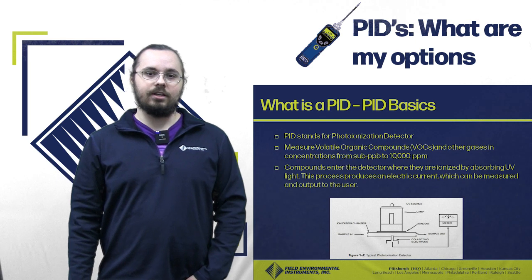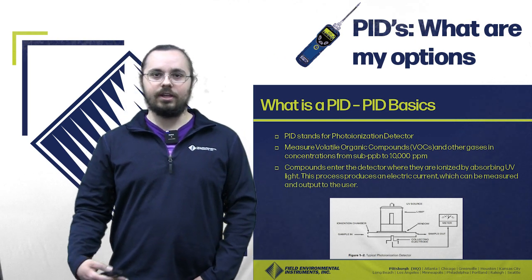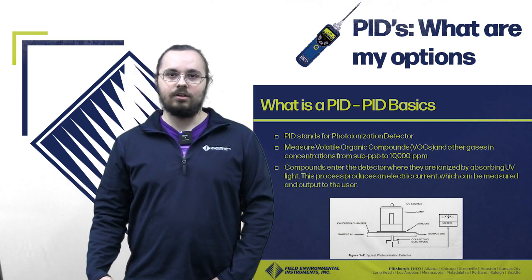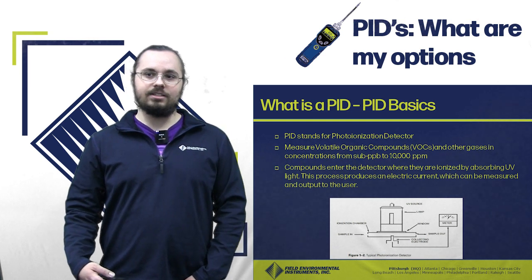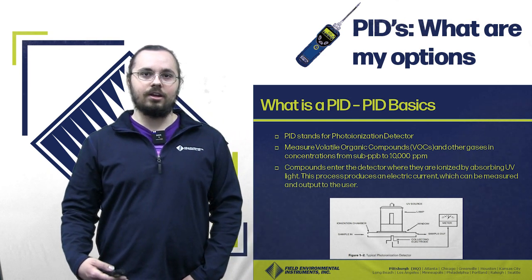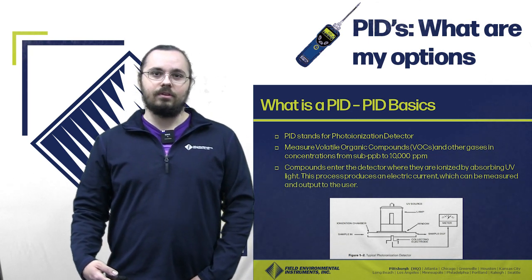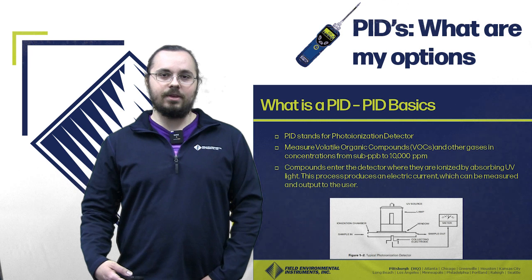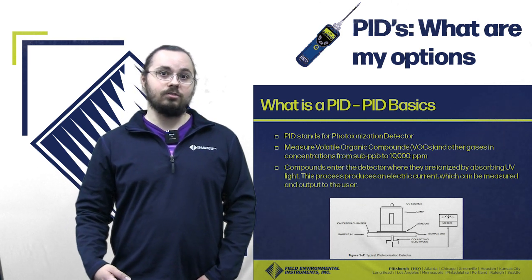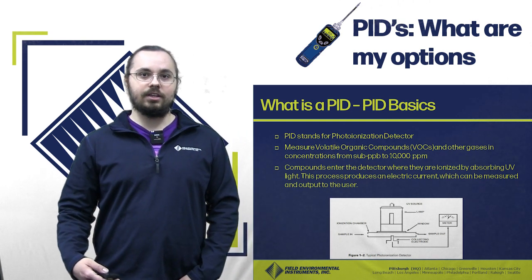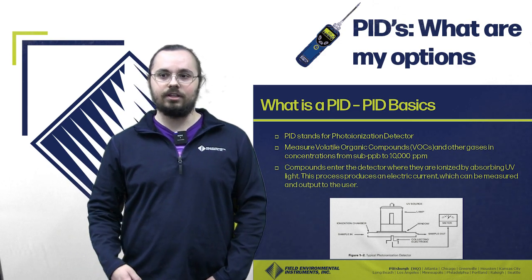Essentially how these work is there'll be an internal pump on them that sucks air into the unit, bringing in whatever compound might be in the air. Once the compound enters the photoionization detector, it is blasted with high energy photons in the form of UV light. In this process, they emit electrons which give off an electric current. This electric current is what the instrument uses to measure the gas in whatever readings it shows on the screen.